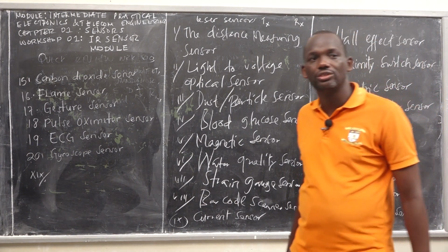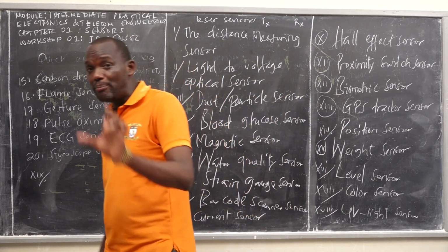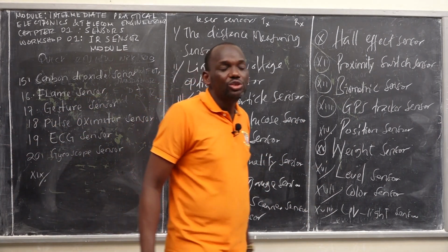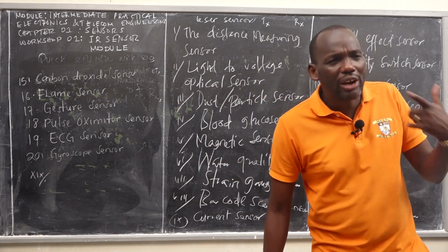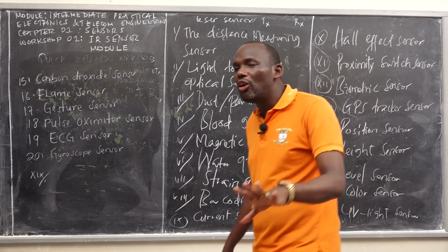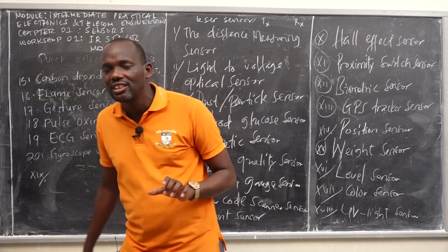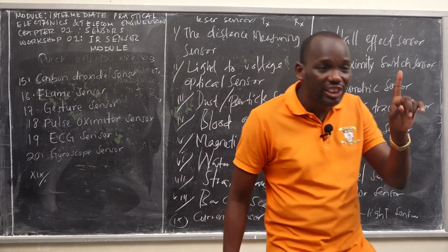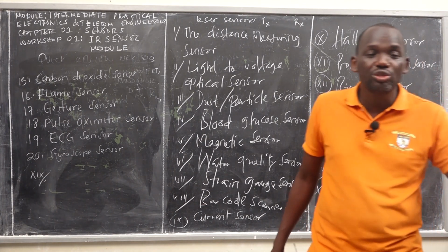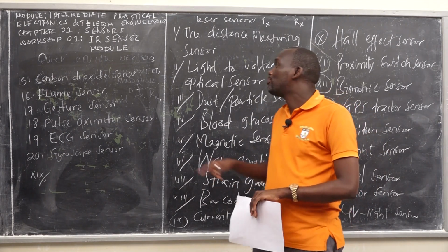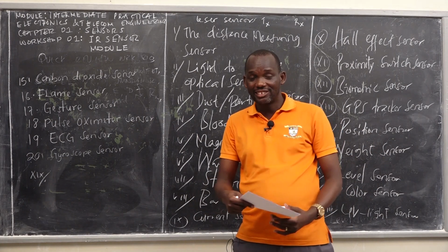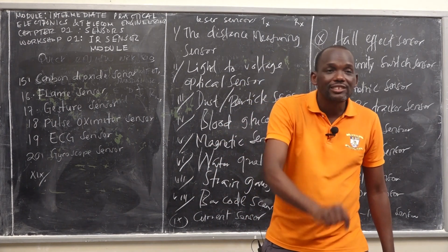Are we together? The dimensions of a coin of 50 and a coin of 500 are completely different. So how does it know that this is 500 Tanzania shillings? That's a good question. They know because before we install them in the particular place, the coin acceptor sensor has to be trained about the particular coin. Before you install it on site, you take the coin acceptor sensor itself and train it to accept 500.